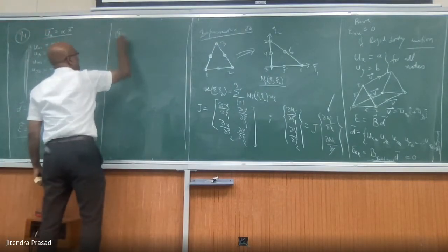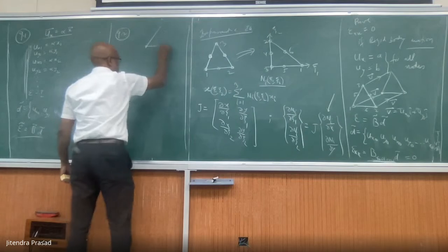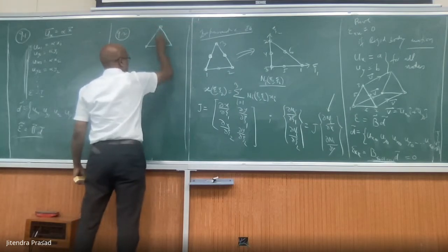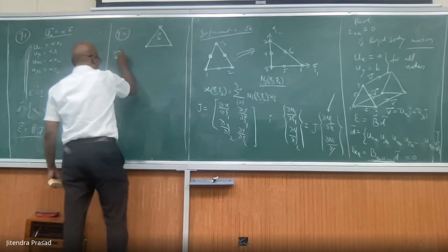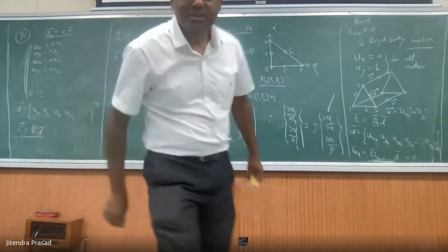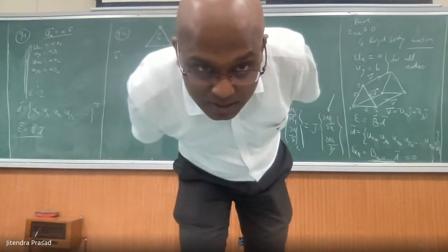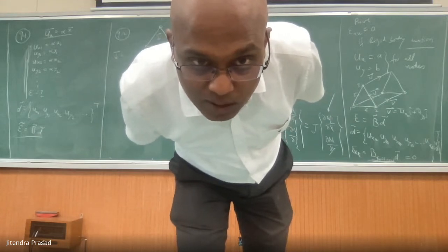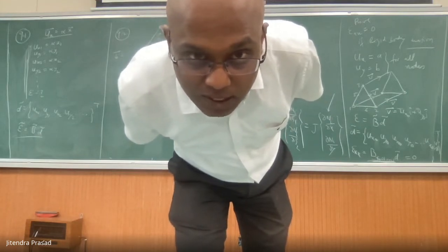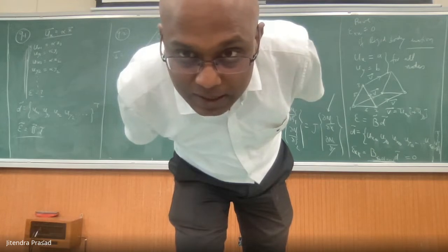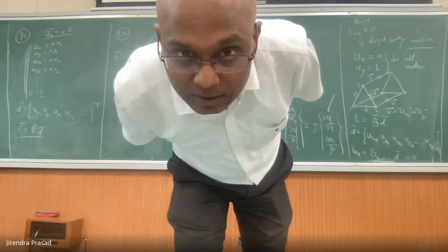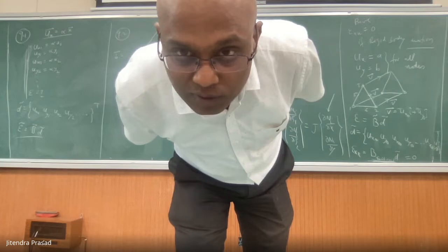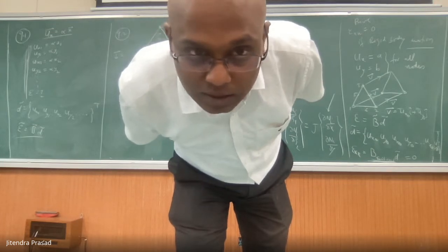Problem 9.2 says that a granular element has a body force b, defined as b equal to bx1 xi1, bx2 xi2, bx3 xi3. Develop the expression for the nodal forces corresponding to this body force.